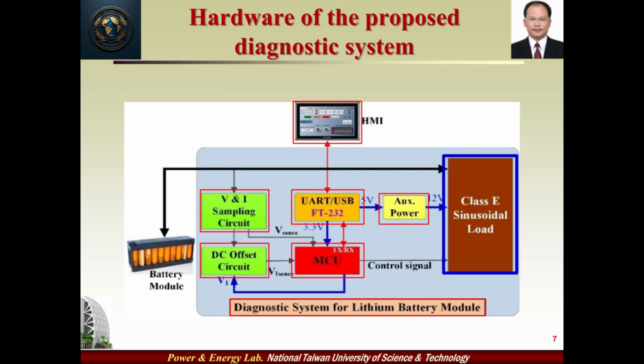This slide shows the system architecture of the proposed diagnostic system, which consists of a sinusoidal load, an MCU, a USB module FT232, an auxiliary power circuit, a signal, voltage, current and temperature capturing circuit, and a DC level offset circuit. In this study, the sinusoidal load is a key part of the proposed diagnostic system.